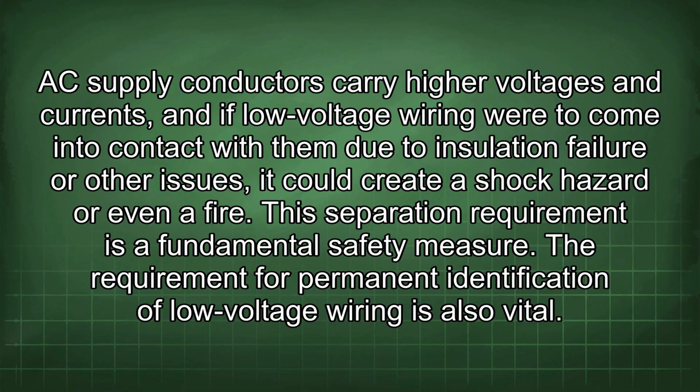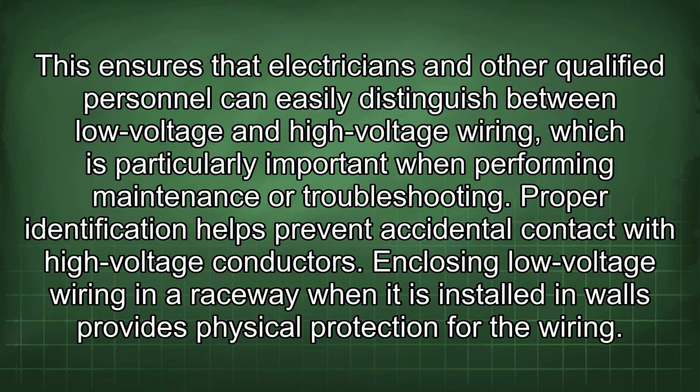The requirement for permanent identification of low-voltage wiring is also vital. This ensures that electricians and other qualified personnel can easily distinguish between low-voltage and high-voltage wiring, which is particularly important when performing maintenance or troubleshooting. Proper identification helps prevent accidental contact with high-voltage conductors.